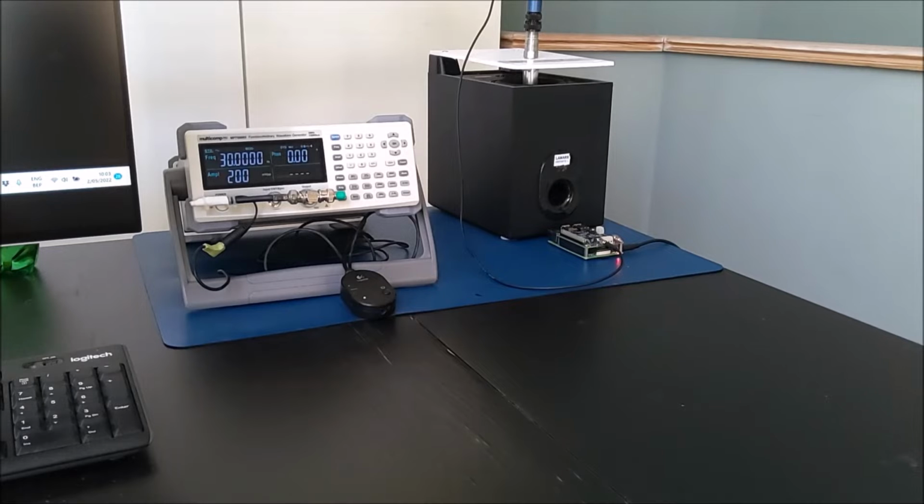And now let's go to the LabVIEW flows and try to see if I can measure the specifications of the shaking device, and then as a second step if I can compensate for it. So the first thing I'm going to do is run that shaking device from 30 Hz to 130 Hz, measure the RMS acceleration along the way and capture that in a spreadsheet. The second step will be to use those values to see if I can compensate over the frequency range for the non-linearities.